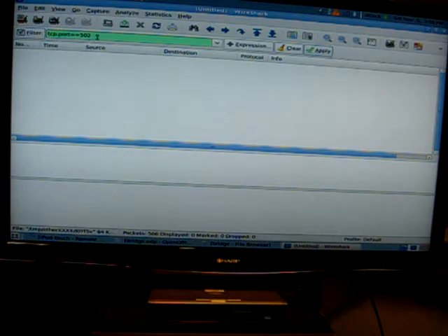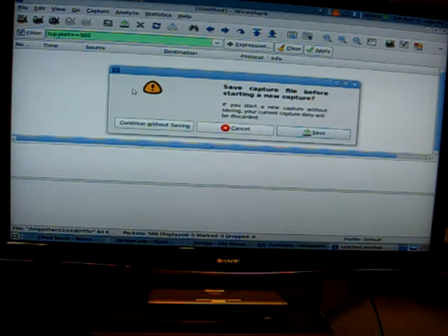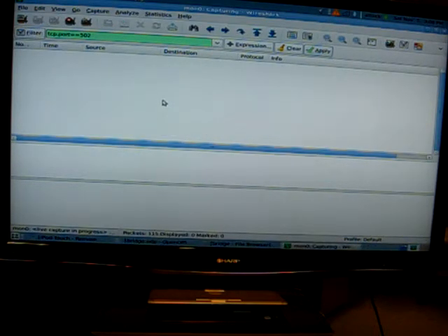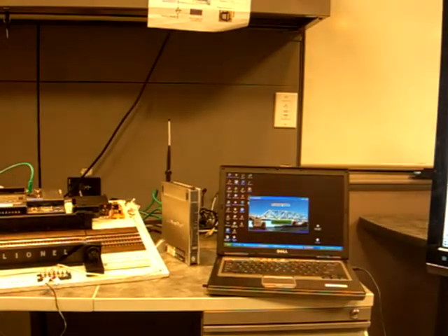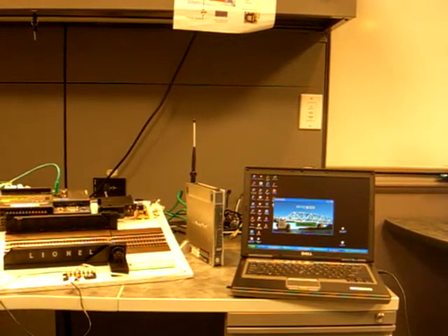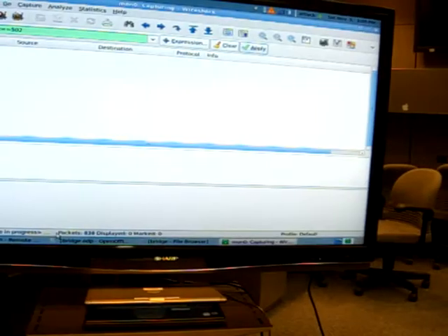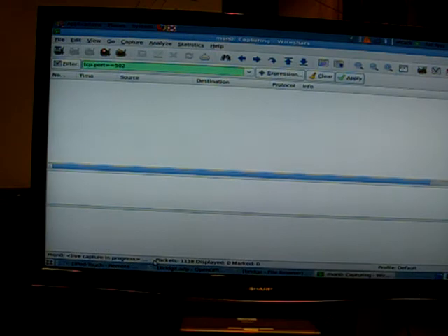We've set the port activity. We're really only interested in those packets that are flying across this network that have to do with the opening and closing of the bridge. That's identifiable through a specific protocol in use called Modbus, and its port number assignment is 502. So we're going to apply that here, and we're going to start up Wireshark. Okay, so it's now operating. We'll go over here and I will open the bridge and watch what happens in our rogue computer.